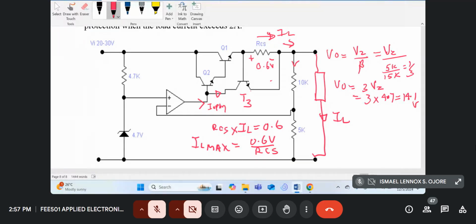It's there to provide short circuit protection. Most of the lab equipment uses it, because they know some students are going to accidentally short circuit the output of the power supply. So to prevent the transistors blowing up all the time, they use short circuit protection.